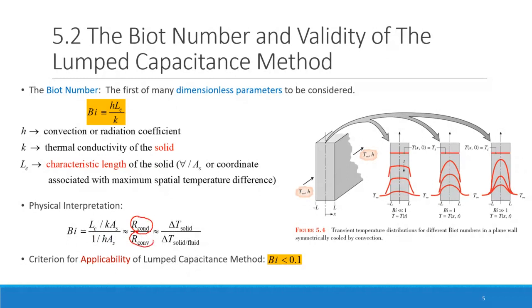One thing I want you to highlight, and I saw a lot of students struggling with calculating it, is the characteristic length. As we said, if we have a plane wall, characteristic length is equal to the thickness of the wall. If we have a cylinder, we apply this equation. Imagine the volume of the cylinder, ignoring the end areas.